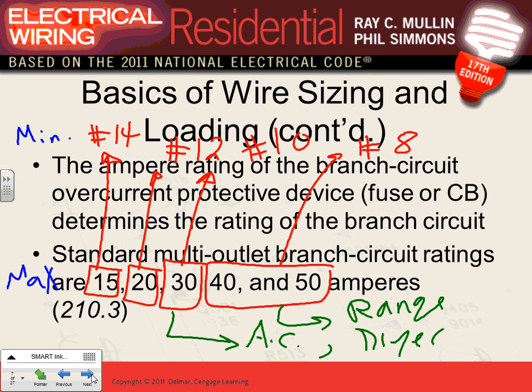In a dwelling unit, again, we're talking dwelling. When you see a 30 amp circuit, typically this circuit is going for a dryer or for an air conditioning. The apartment that you guys have an air conditioning, not a window air conditioning. If you have a window air conditioning, you can get away with 20 based on the size. If it's standalone, outside, split unit air conditioning, then you're going to end up with a typical. These are typical, guys. You still need, we do calculation, but typically this is what you do.